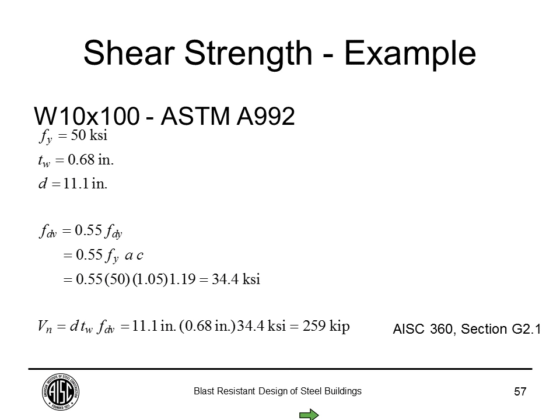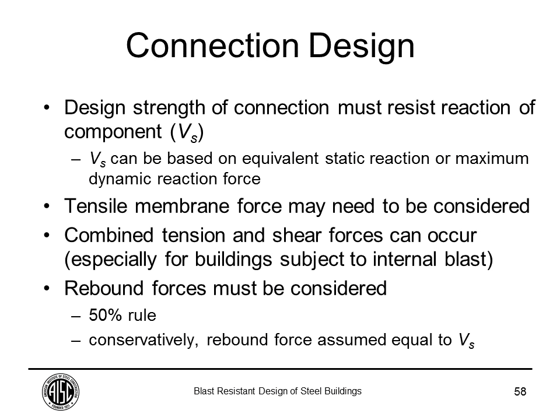Depending on the design that you're working on, some specifications allow the inclusion of LRFD phi factors. I think we should include them when we can. Some other specifications tell you to use just 1 because they realize we're already designing for ultimate capacity, so there is some conservatism already. So this is kind of what I'm discussing right now.